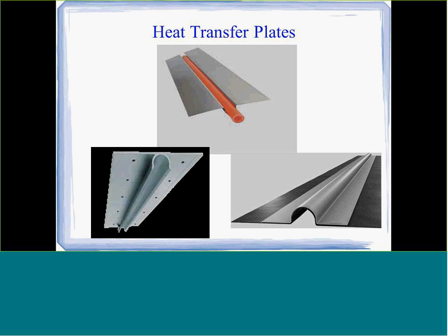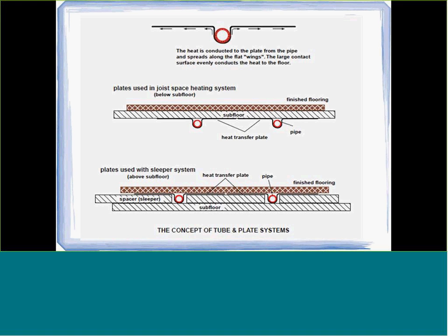Heat transfer plates. A lot of times when we quote these jobs and we add heat transfer plates, they can be kind of pricey depending on which kind of heat transfer plate you're going to be using. And we have people who say, well, I want to do it without the plates. The plates are exactly what they say. They transfer heat. They make the system more efficient. And the added cost of a heat transfer plate usually pays off in both energy savings and creature comfort. You get better heat from a heat transfer plate than if you just attach the tubing by itself.